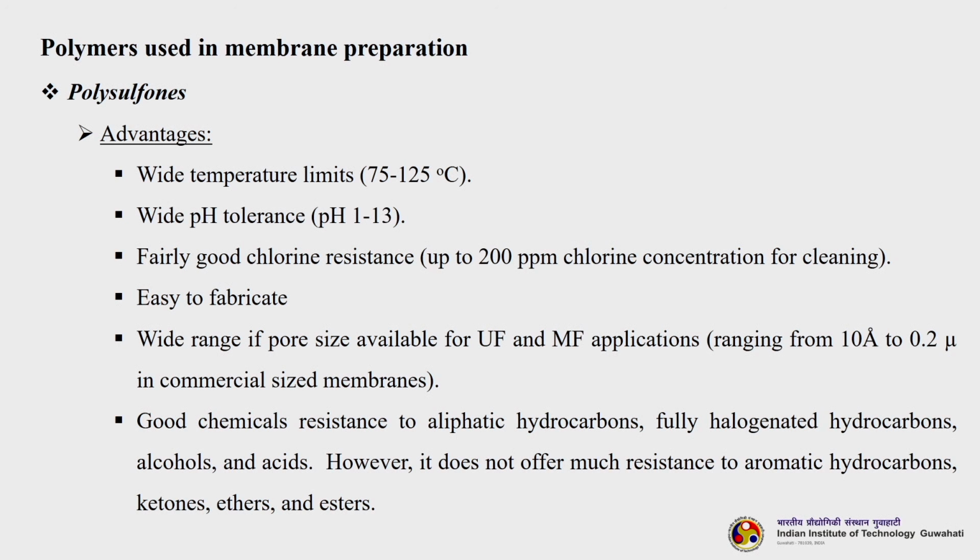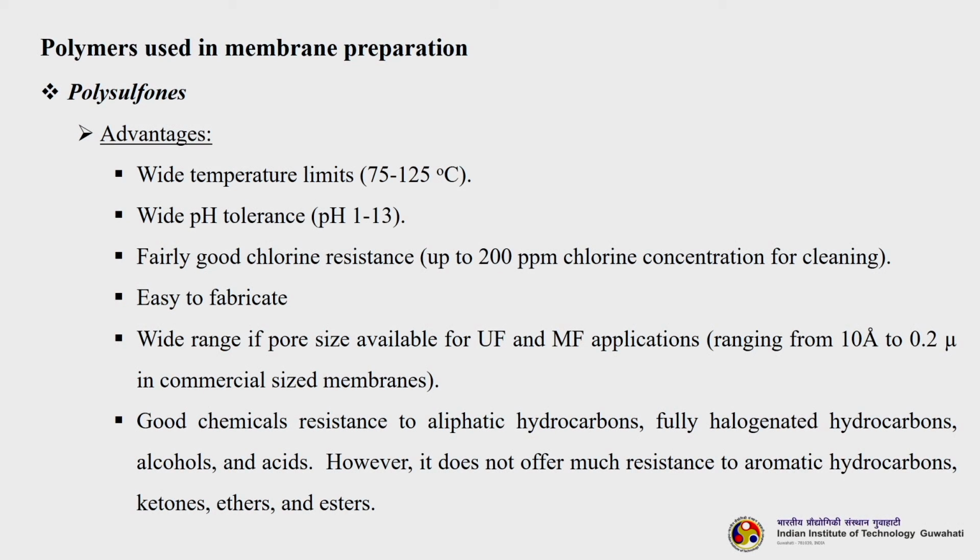So, for cleaning purposes this type of membrane will have no problem while it deals with chlorine, and it is easy to fabricate, with a wide range of pore sizes available for ultrafiltration and microfiltration applications. So, we can easily prepare either microfiltration or ultrafiltration membranes using polysulfon material. It has good chemical resistance to aliphatic hydrocarbons, fully halogenated hydrocarbons, alcohols and acids. This means that polysulfons have extremely good chemical stability towards most of the chemicals and solvents. However, it does not offer much resistance to aromatic hydrocarbons such as ketones, ethers and esters.